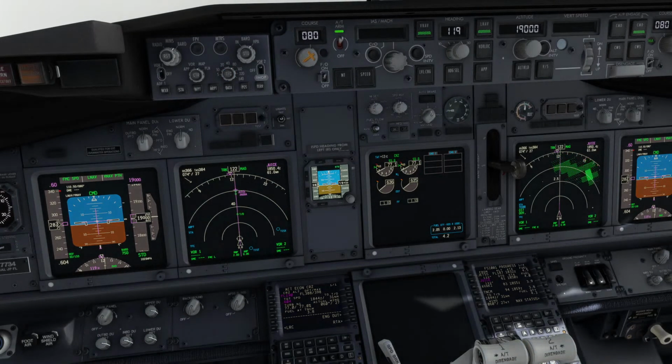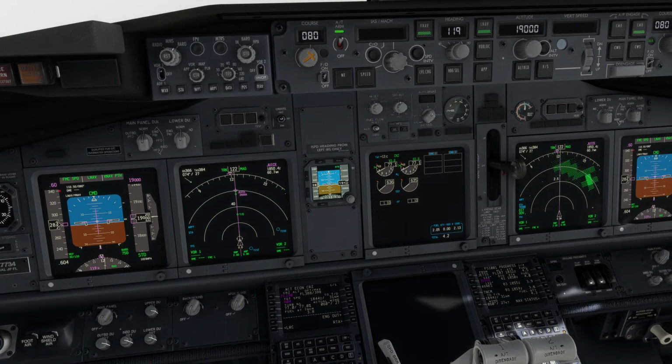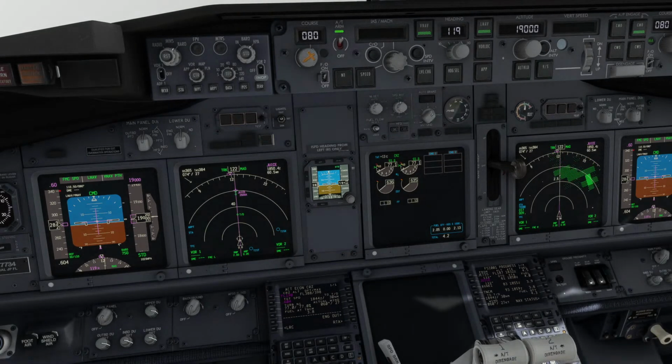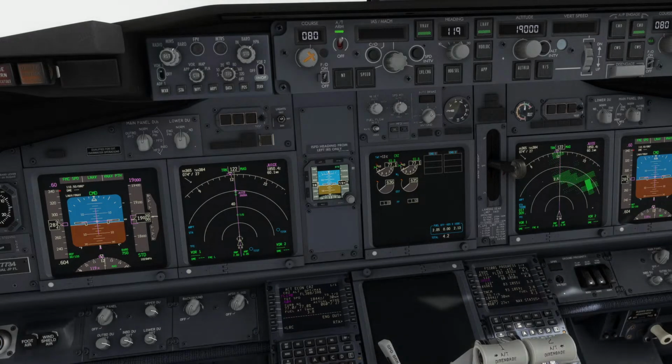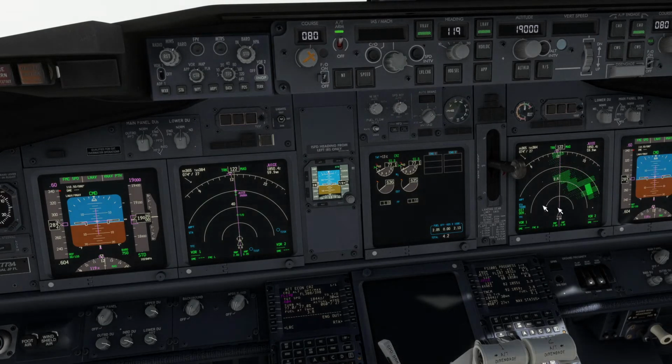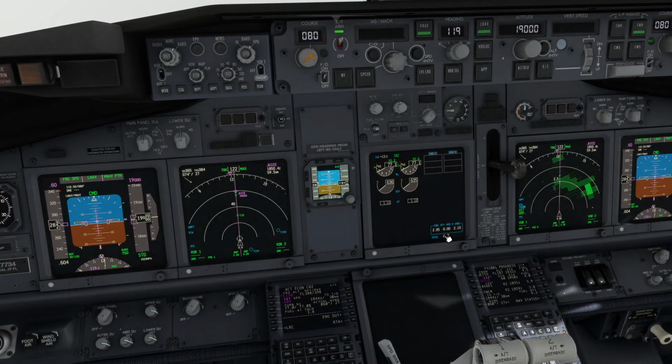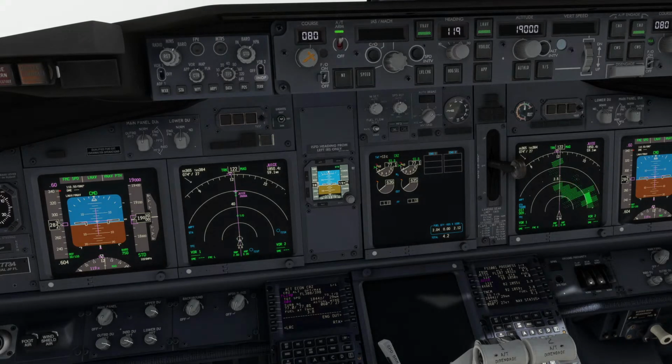once we extend our landing gear, we cannot retract it, and as we cannot retract, we'll have more drag, and most probably this fuel is not enough for us to reach any other airport than the one that we are going to right now.